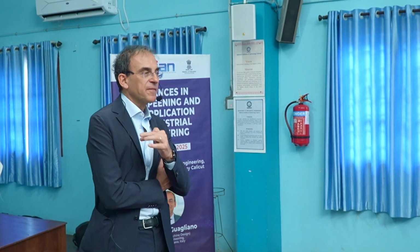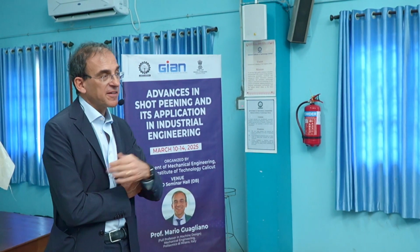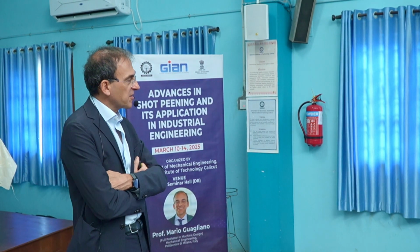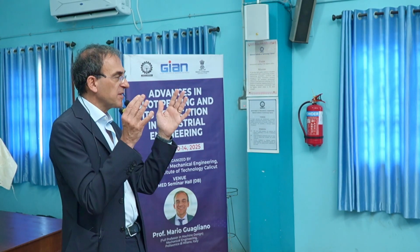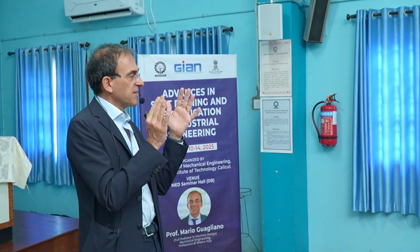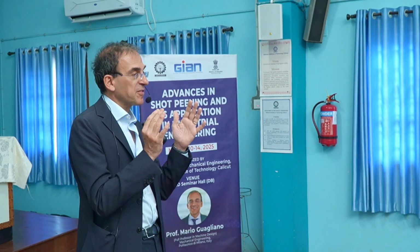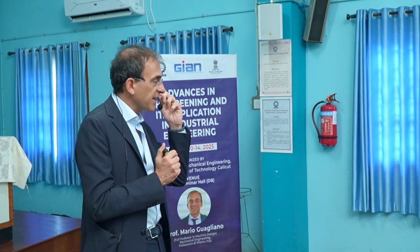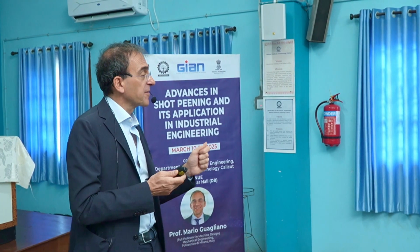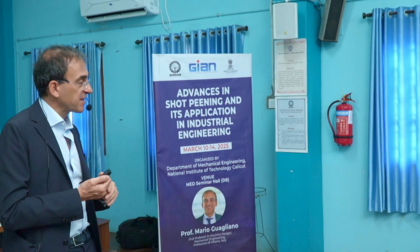During the first 10,000 cycles, we partially lose the residual stresses. So what is important is that we have a suitable depth where we have compression. So even if they are going to relax and are a bit reduced, the effect of compressive stress remains valid. This is valid especially for steel and high-strength material.